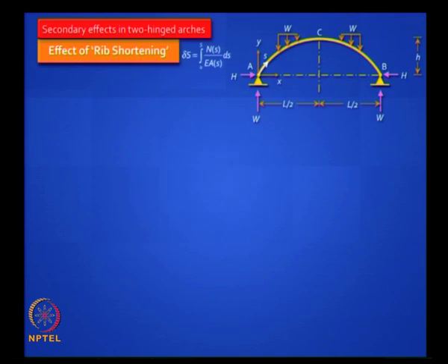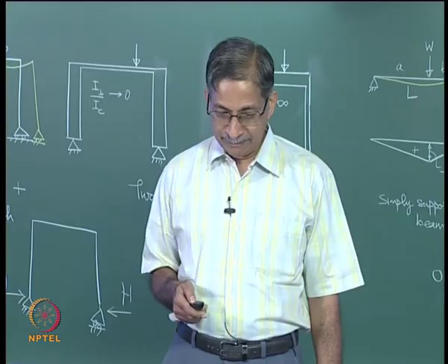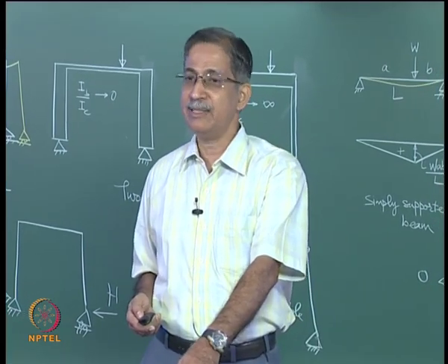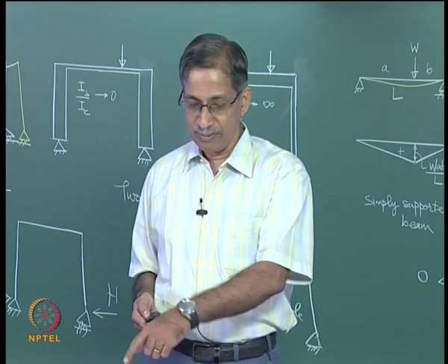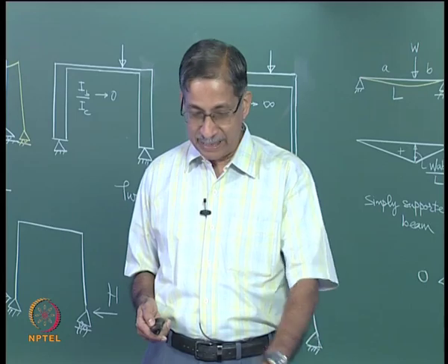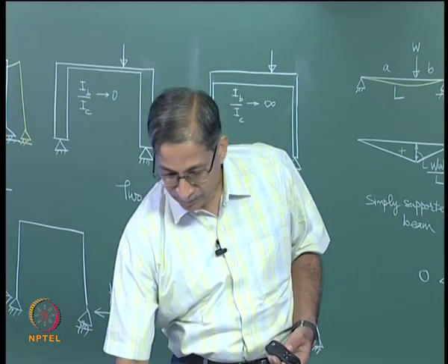So do not forget your fundamentals, just have to include that second component of axial strain energy, then you invoke this theorem. When you invoke this theorem, you get an additional term, right, where you account for the axial thrust, and when you substitute in your capital H, you can prove this, the final form takes this shape.